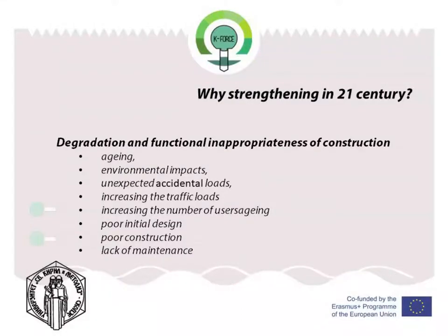The issue of upgrading the existing civil engineering infrastructure has been one of great importance for over a decade. Deterioration of bridge decks, beams, girders, columns and buildings may be attributed to aging, environmentally induced degradation, poor initial design or construction, lack of maintenance, and to accidental events such as earthquakes. The infrastructure's increasing decay is frequently combined with the need for upgrading so that structures can meet more stringent design